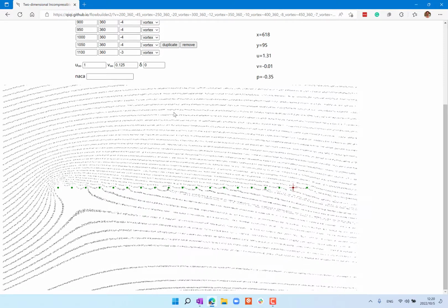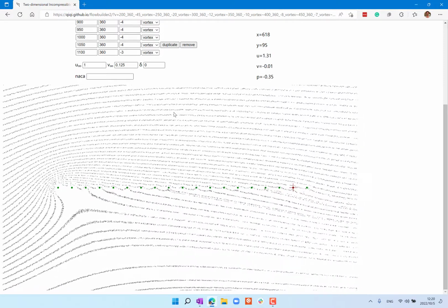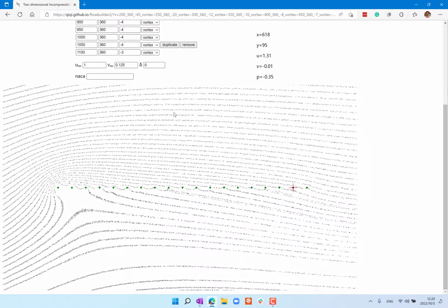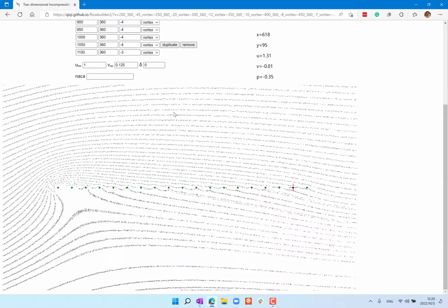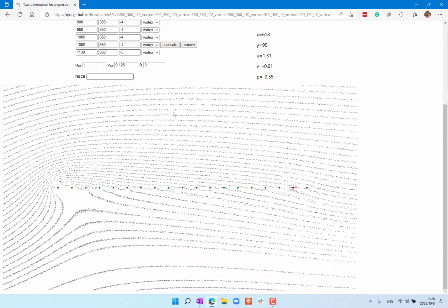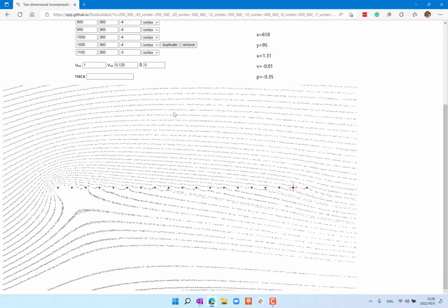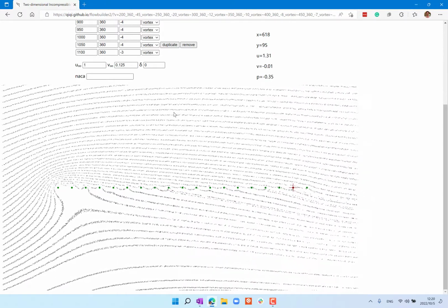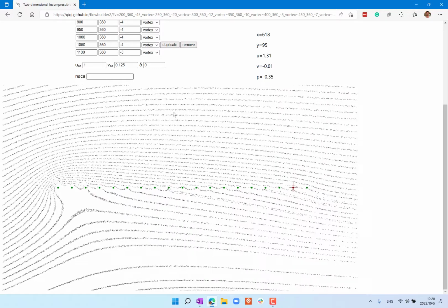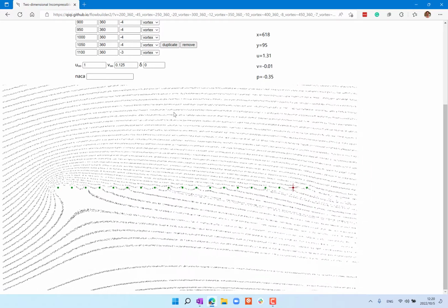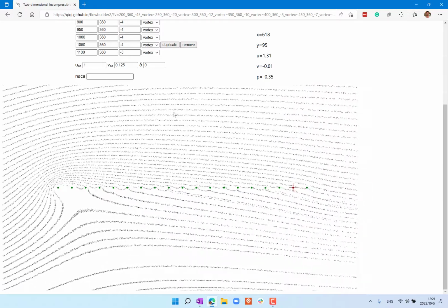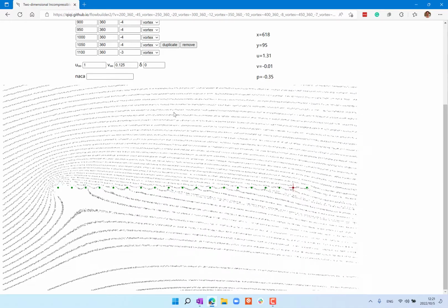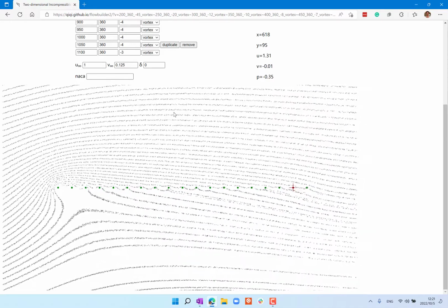And that increases the lift by a factor of 2 without changing the distribution of lift at all. Do you agree? Because at every location the vortex just increases and the pressure difference at that location just increases by a factor of 2. So there is no effect on the distribution of the lift except for doubling the lift if I increase the angle of attack by a factor of 2.